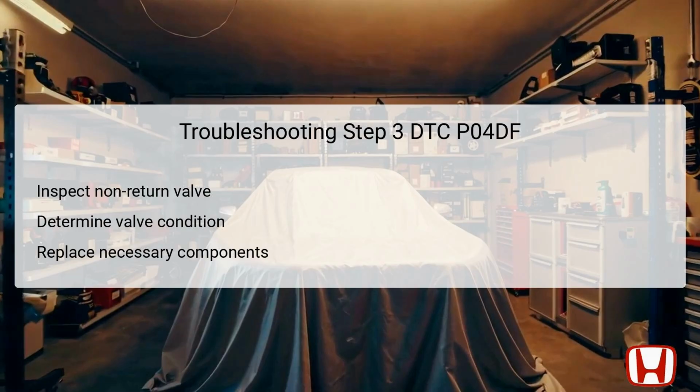Inspect this valve for any signs of malfunction, as its role is to prevent backflow of vapors, thus ensuring the correct pressure within the system. The evaluation should include looking for physical damage or blockages that could impede its function.